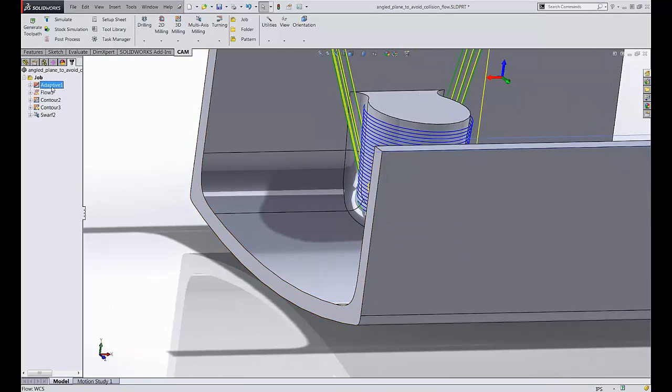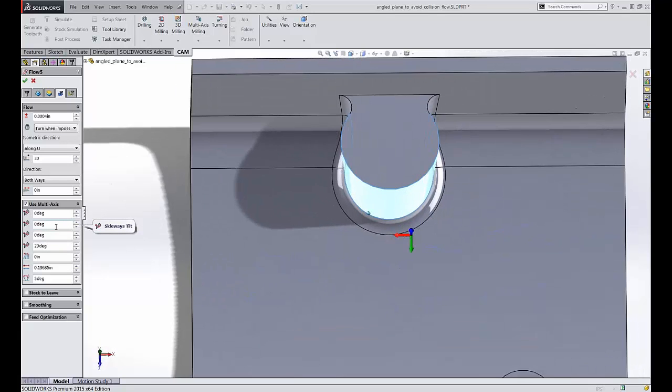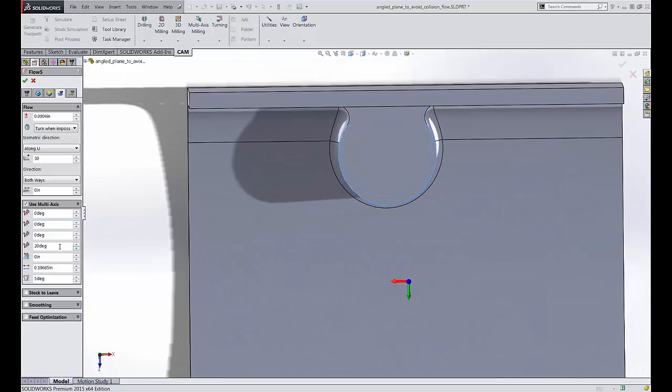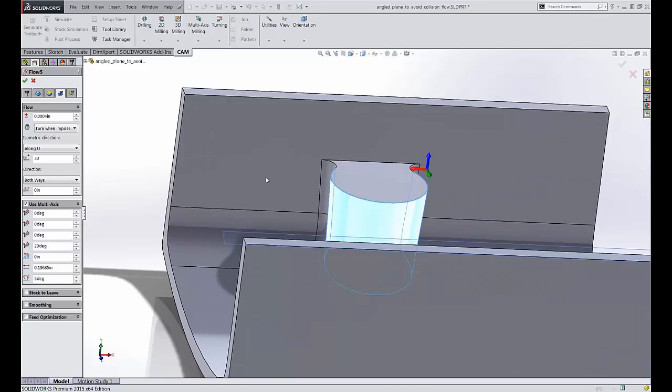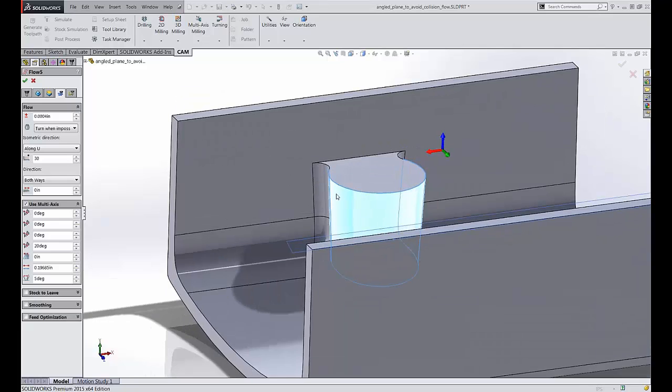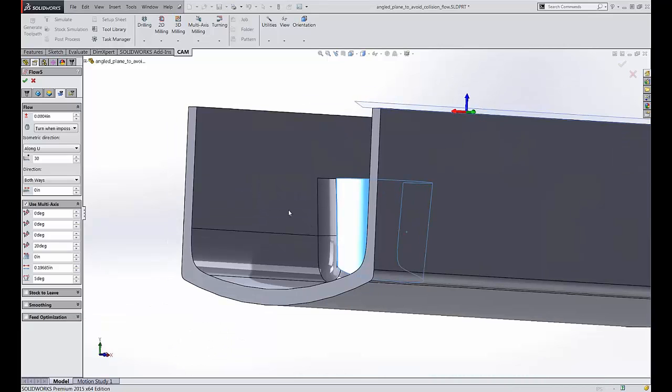You have some handles that you can pull in here. We already have our maximum tilt, and that's probably what we want. We could apply some sideways tilt, but as viewed from the top, that sideways tilt is already being limited by our maximum tilt. That's the same handle, right? Our passes are running this way, so our tilt wants to tilt this way. Our actual tool, our normal to the surface, is coming off of here in the negative direction. So we're already massively modifying that. We're only allowing it to go 20 degrees, so it's way tilted.